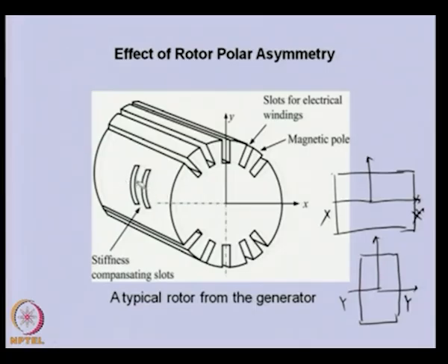But even with that we have variation of the stiffness as the shaft rotates. So, we can see that when it has a different orientation, there will be a change in the stiffness. So basically for such a system, the stiffness changes with time, and this particular behavior gives instability to the rotor system.